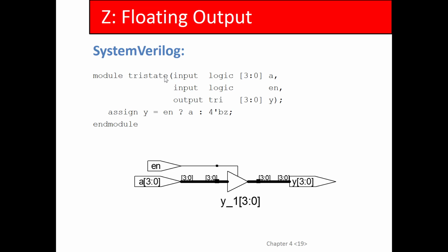But yet, if I say 4'bZ, would that not be 0, 0, 0, Z? No, apparently Z is special. See, I wouldn't trust this. You're assuming that I would have put 4'bZZZZ just to make it clear that I want 4 Z's.